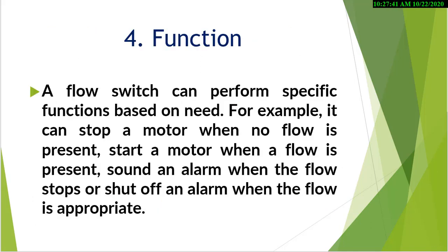A flow switch can perform specific functions based on need. For example, it can stop a motor when no flow is present, start a motor when a flow is present, sound an alarm when the flow stops, or shut off an alarm when flow is appropriate.